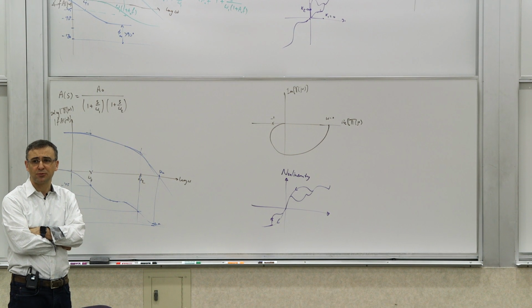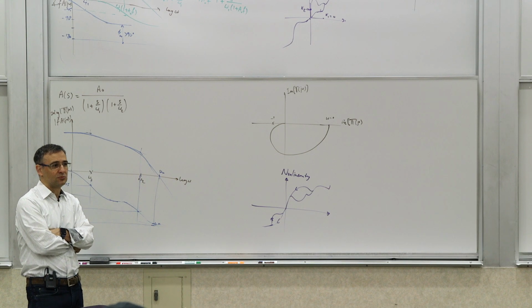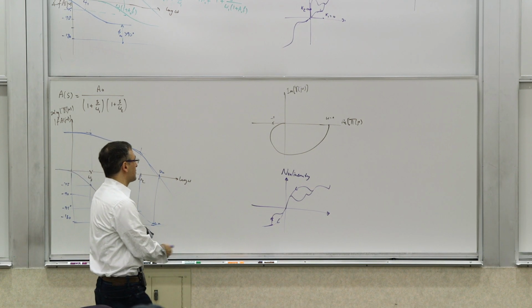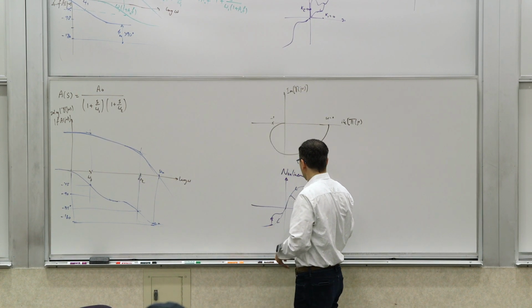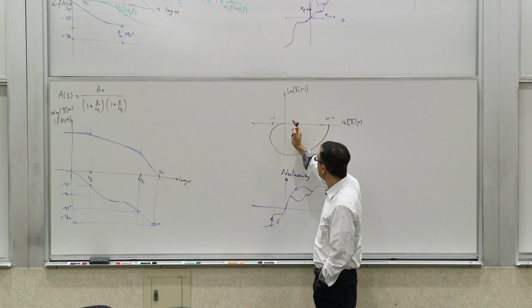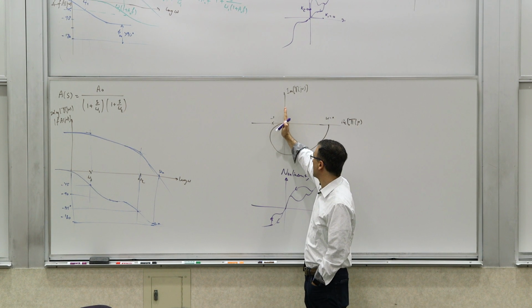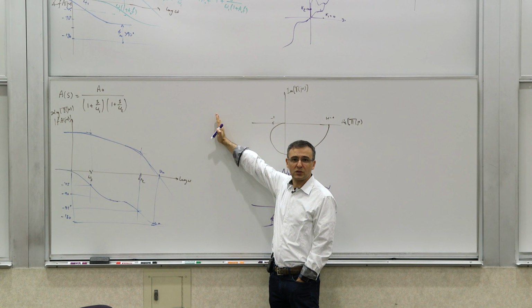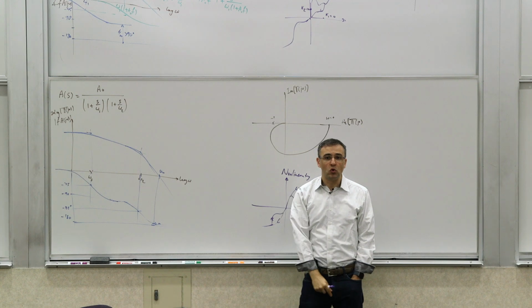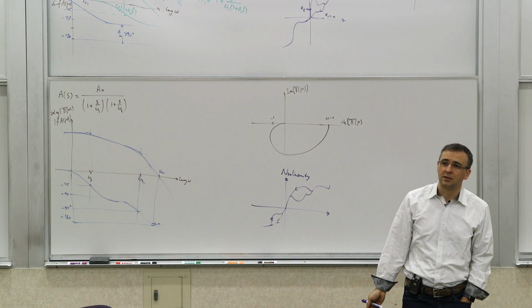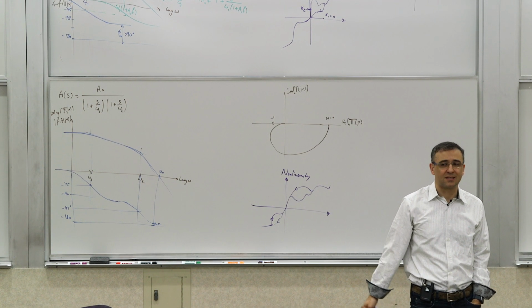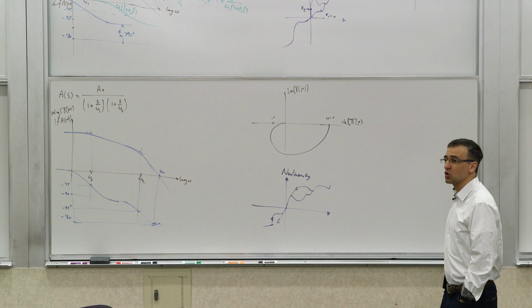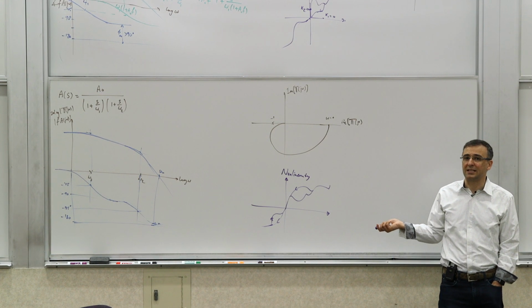Can we guarantee absolute stability? No, right? Because this corresponds, as we just said, to the circle criterion. Basically, what this would say is the circle would encompass the entirety of the left half side of this Nyquist plot. So you are going into the circle, because the circle is the entire left half side of this plot. So you can't guarantee stability based on this.